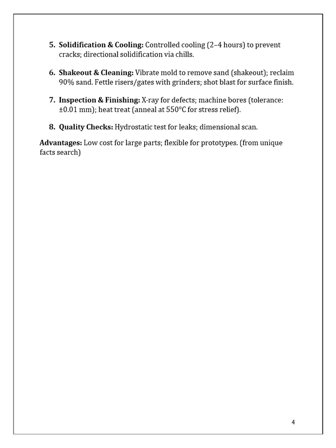They anneal at 550 degrees for stress relief. Quality checks: hydraulic test for leaks and dimension scan. Advantages: low cost for large parts, and flexibility for prototypes and unique shapes.